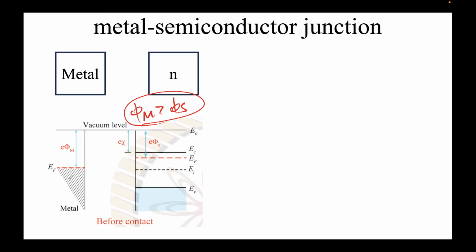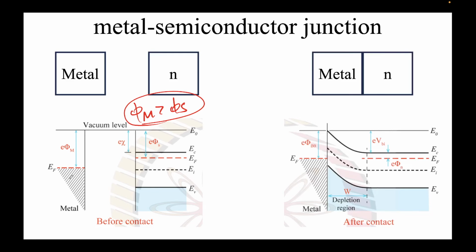It's very similar to what was happening with the concentration gradient in the PN junction. The electrons from the N side were traveling to the P side, they recombined, and they formed the depletion region. So again, the depletion approximation that we saw there applies: the electrons have traveled from this region and they leave behind positively charged donors.